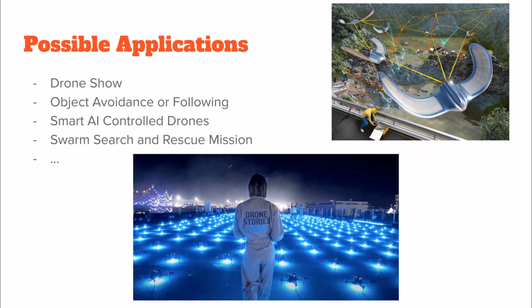Okay, now that we know the concepts and logic behind offboard control and the risks it has in operation, why do we even need to use offboard control? The truth is, for most applications, we don't even need offboard control. The Pixhawk and PX4 controller can do everything for you and manage the risk and let your drone do the operation safely. But for some advanced applications such as drone shows, at least by the time I'm recording this video, you need to use offboard control.